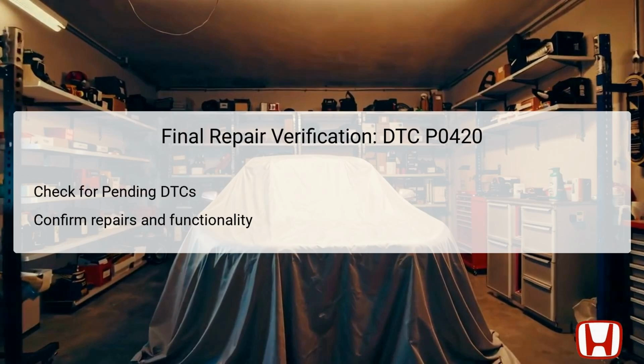The final verification, after completing all previous steps, is to check for any pending or confirmed DTCs using the HDS. This process ensures that all systems are back to normal parameters after repairs and that no new issues have emerged. If the P0420 code or any other DTC does not reappear, it suggests that the repairs were successful and the vehicle is functioning correctly.